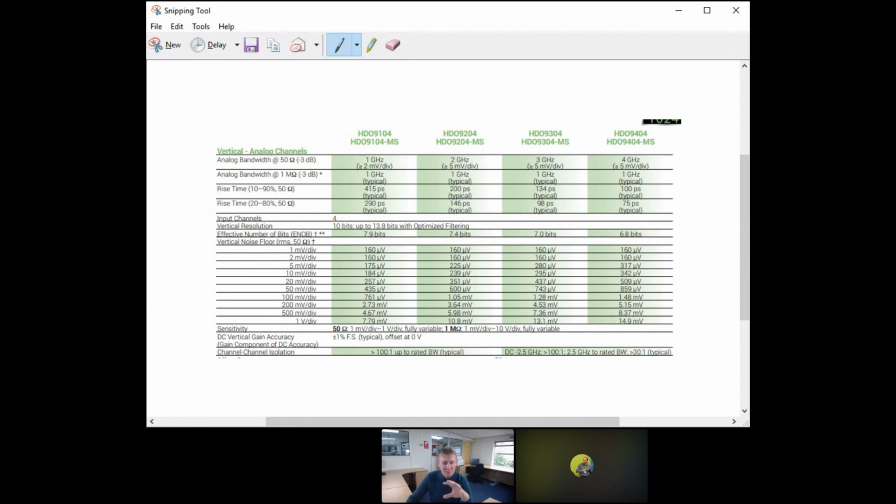you have to be aware, certainly, and I remember my supervisor years ago pulling me up on this. We have to understand the native accuracy of the equipment. So I thought I'd just pull this one up here. Now, this is an example of a fairly reasonable quality oscilloscope, and you can see here that the gain accuracy, so the vertical accuracy, is about plus or minus 1% of the full scale, and there are some offsets as well that you sometimes pick up.